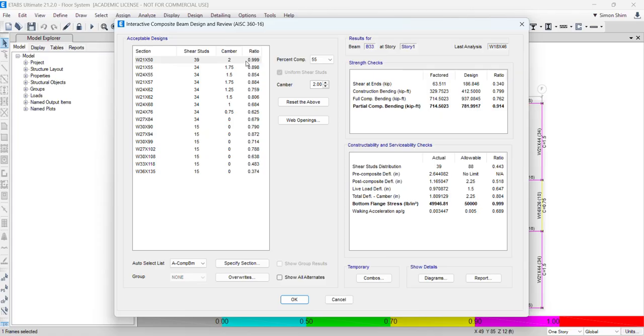So when the wet concrete is loaded, the beam levels out to flat. In many cases, for a long span beam with a heavy dead load, in ETABS and in our engineering practice, we use camber. So those are all the calculations you need to get used to. This is the heart of composite beam and steel floor framing construction and calculations.